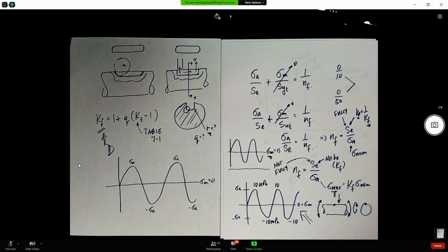One is a spring that's not rotating. The other is the plate with the hole in it. Look at those because they deal with a non-rotating cross section where you have to use the equivalent diameter D in your KB value. But if you have limited time, focus on the shaft solutions.